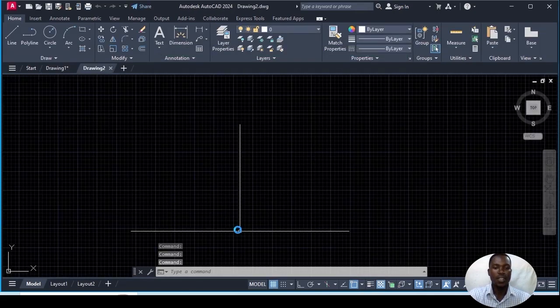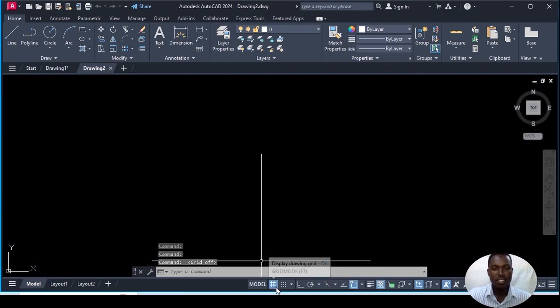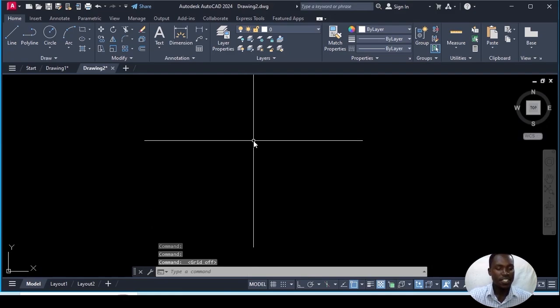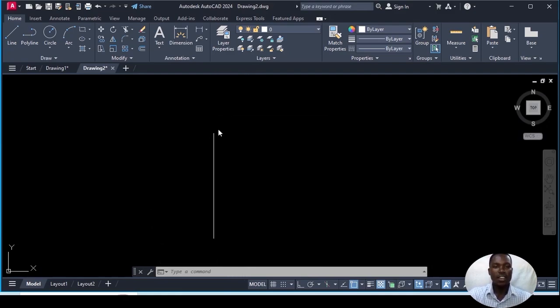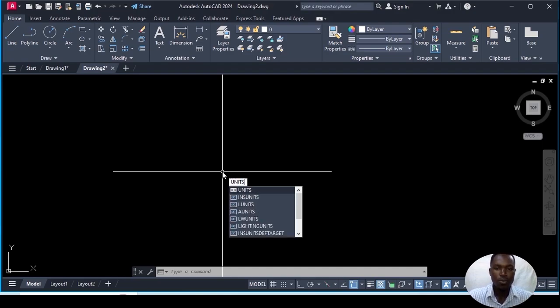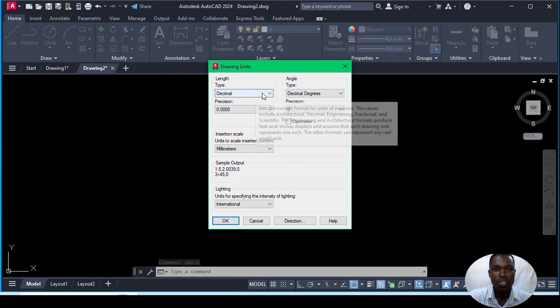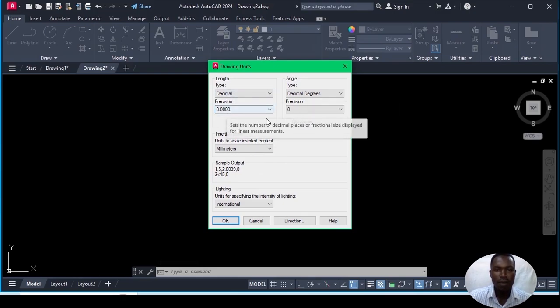Press and we open. So with the AutoCAD ISO WT, simply the difference is that the units are varying. If you want to check the units of this AutoCAD ISO WT, we just type units. Just type units to bring it up here, and when you click there, we will find the details. It is decimal, and precision is the number of decimal places.